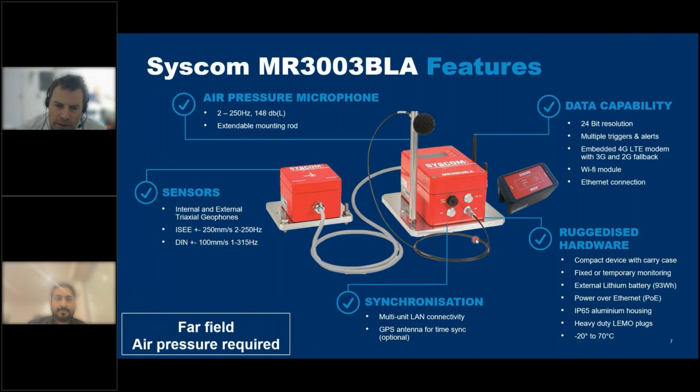And the big plus with these devices is that they are built really for remote real-time monitoring, so it embeds a lot of communication technologies. Obviously, the purpose being you monitor permanently 24/7 what's happening on your mining sites for blasting-induced vibrations, but also for all the other vibrations happening on site, for a better understanding of your mining and maybe rock mass structure, etc. So that's the first one.